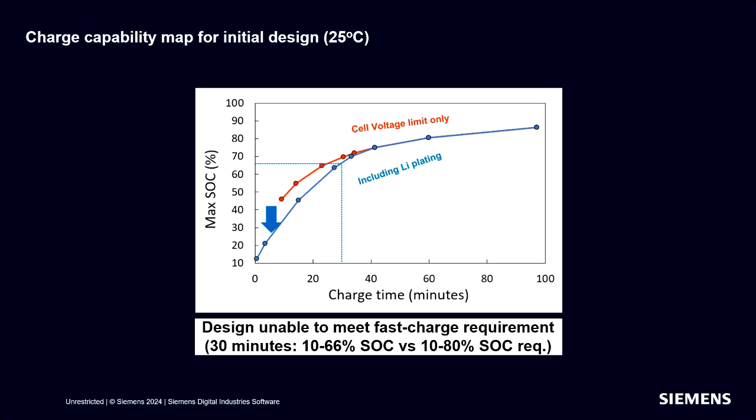We observed that the initial design here is unable to meet the fast charge requirement, which I mentioned was going from 10 to 80% within 30 minutes. Here we only go from 10 to 66% SOC in 30 minutes. So we take the value of the blue curve if we include lithium plating.